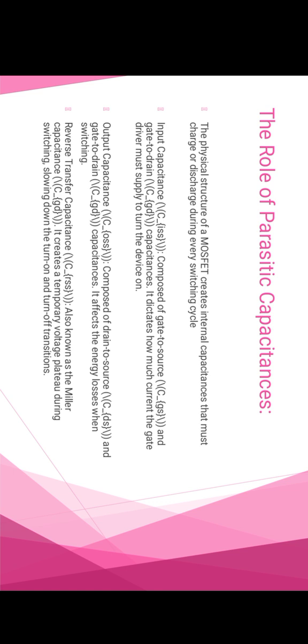Next one, output capacitance. It is composed of drain to source and gate to drain capacitance. It affects the energy losses when switching. Fourth one, reverse transfer capacitance. It is also known as the Miller capacitance. It creates a temporary voltage flux during switching, slowing down the turn on and turn off transitions.